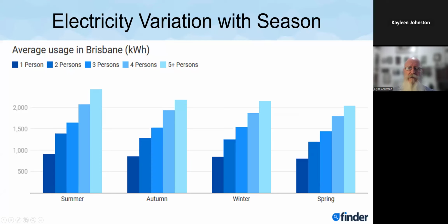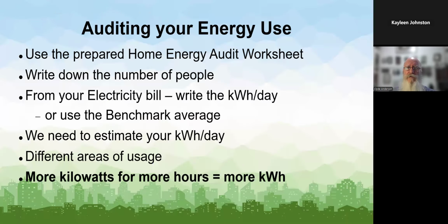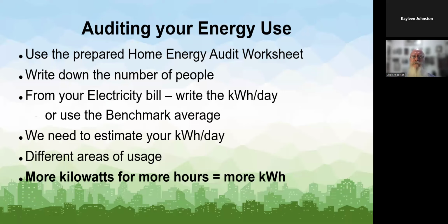So how do we do an energy audit now? Hopefully everybody's got a copy of that home energy audit worksheet that we sent out. I'll show you what that looks like shortly. This is an easy way to keep track of everything and make sure you don't miss anything. The idea is that in your home energy audit worksheet, up the top, you've got how many people are in the house. That makes a difference.